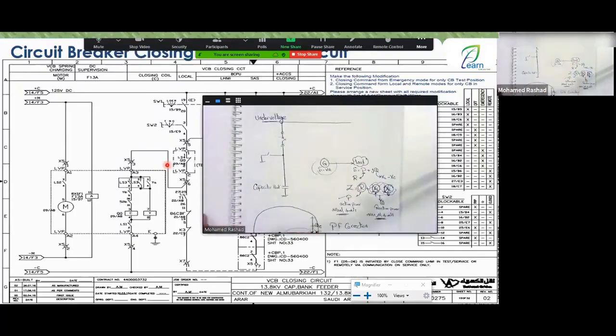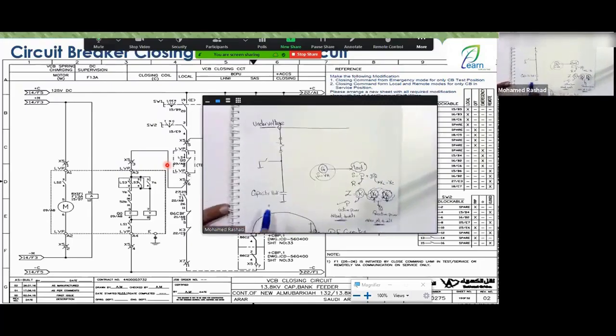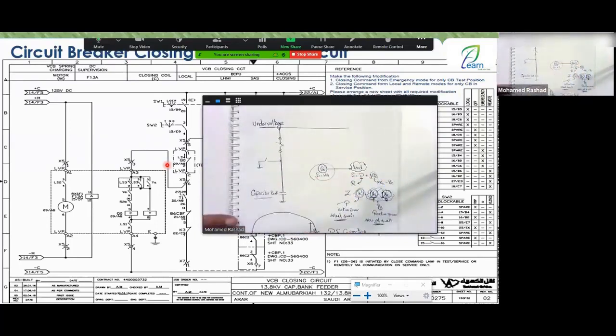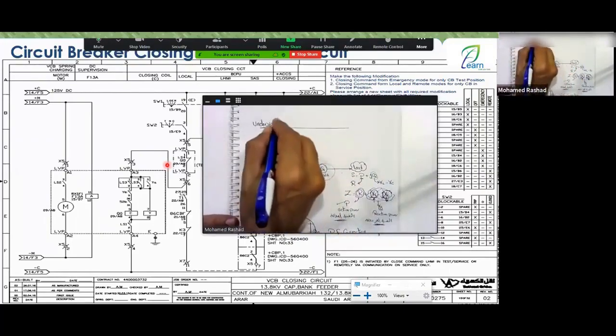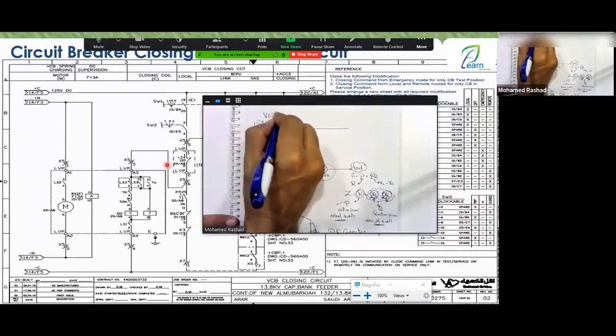So you have another source providing Q, not the generator. Who would be the capacitor bank? And thus I reduced the Q from the generator, and thus reduced the active power drawn from the generator, and thus the quality returned. I started to have under voltage, and the voltage returned again.